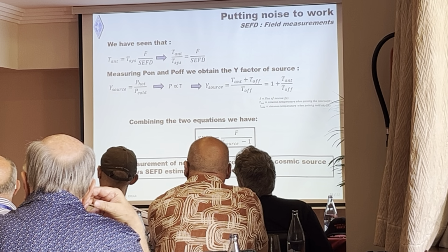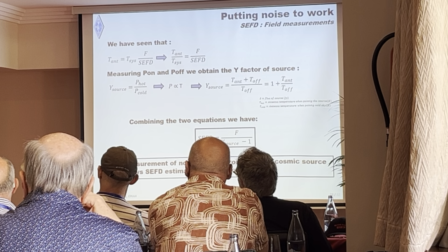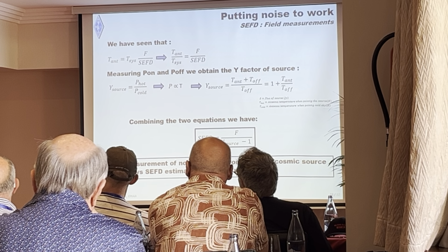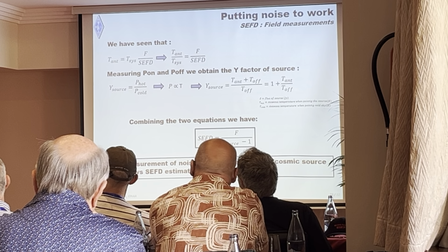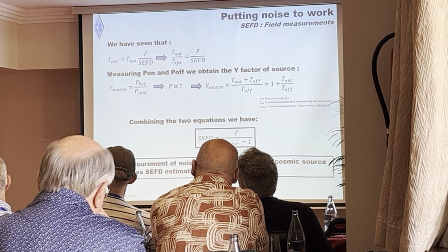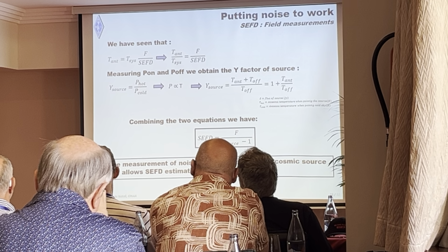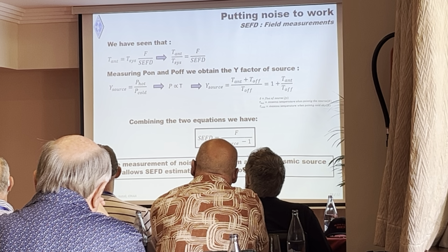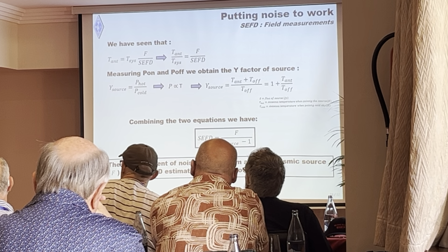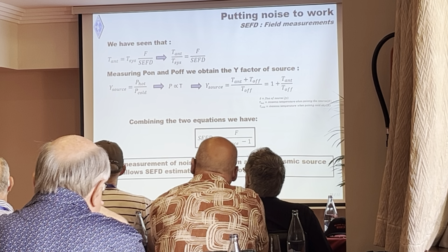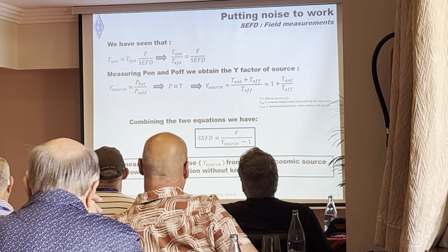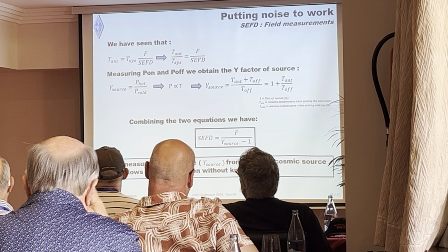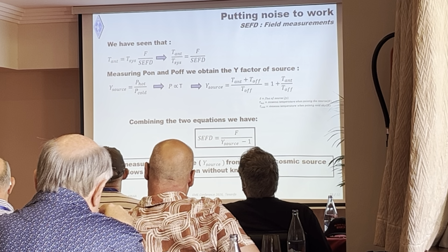You don't need to put the fantastic number that is the dish efficiency. I'm using 50, I was using 60, maybe I use 45. You don't need to do that. You have a number that characterizes it, and this number is not forgiving. So we cannot play with it using another efficiency of the antenna. This number characterizes entirely your station, the receiving part of course.